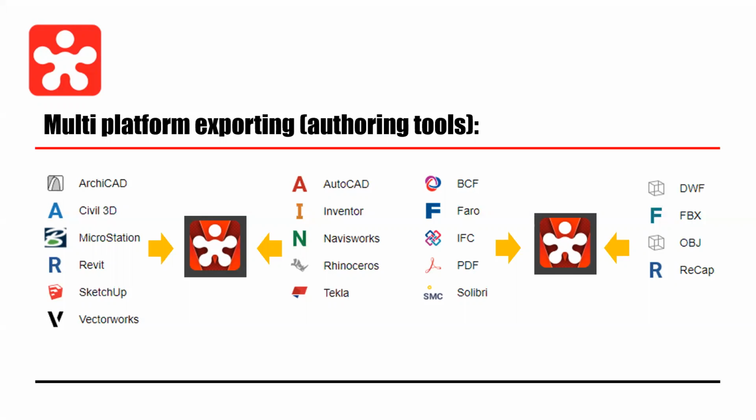But if you're caught in this workflow of generating IFC files or maybe FBX files, there's a pitfall to that as well. If you have an IFC, you do get an accurate model with the data-rich objects we all want to see in a BIM model. However, the file size can and usually does become extremely large. And in most cases, you lose the graphic qualities in the file exchange.